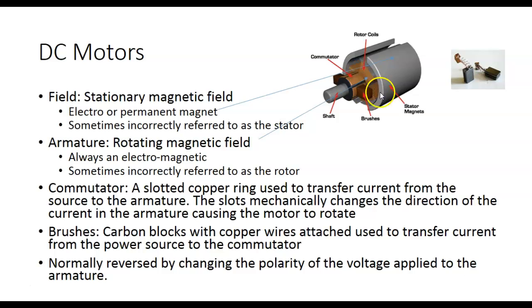So a DC motor has to have a wound rotor, it's got to be wound. And of course it's copper and it costs a lot of money. Plus, when you look at that thing, these brushes are going to wear out. So on a big DC motor, you will have access to those brushes, so you're going to have to replace them every once in a while, right? You understand? And also, when these things switch, there's going to get garbage on the commutator.